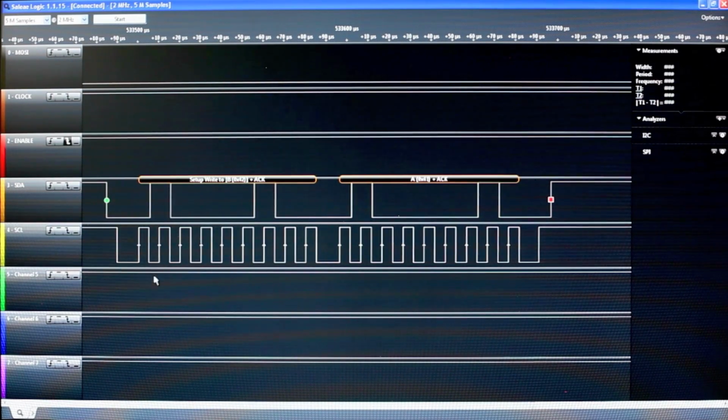So there's our start bit. And then you remember how we shifted the data 1 bit, because the internal code that you don't see is going to shift that automatically and then add the read-write bit accordingly. And that's exactly what's happened here. So the 42 that became 21, well, back in here, it's now 42 again. The analyzer has interpreted this as 42. So let's check the transitions.